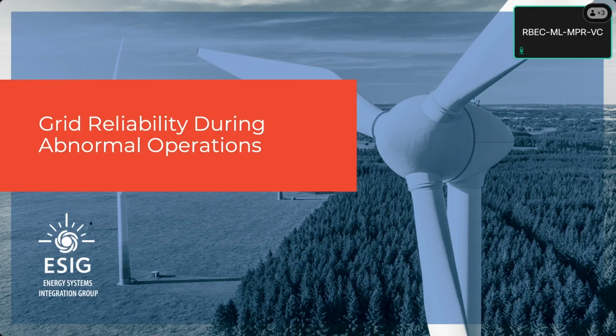And then to Andrew's point, personal experience, and this was in a place I won't name. It was once its own country, and I lived there. There were 2 plants, same developer, one breaker away in a ring bus, so fairly close electrically. They interconnected one facility, then they interconnected a new facility. The new one was fighting with the old one. The simplest thing would be to tune them both at the same time and change the voltage groups and make it work. But even the manufacturer, the developer didn't want to change one set of parameters because it opened them up to liabilities. So we tuned around the other problems when the easiest solution was just to open them both up and tune them together.